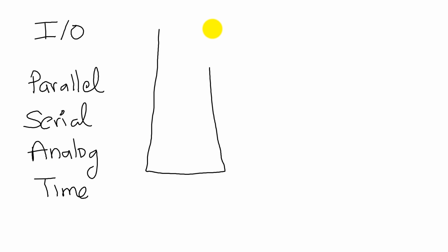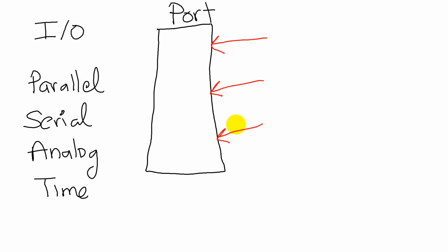So we're going to create a reconfigurable port. And a port will have two types of signals. We could have input pins, which allow digital signals to enter the computer. Remember here, they're 0 volts or 3.3 volts. And when we input, this logic level is converted to a true or a false, a 0 or a 1, where 0 is mapped to 0 and 3.3 will be mapped to 1.